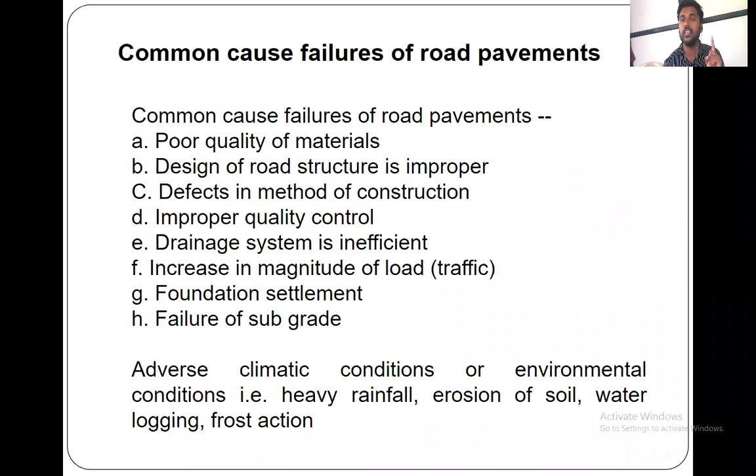Okay, so the first and most important thing is what? Poor quality of material should not be used. This is the first common failure. If we use poor quality material, ultimately what will happen? Suppose instead of angular coarse aggregates, we are using rounded ones. So what will happen? Whatever the force of attraction between two molecules, the cohesive bond and adhesive bond, will not be proper.